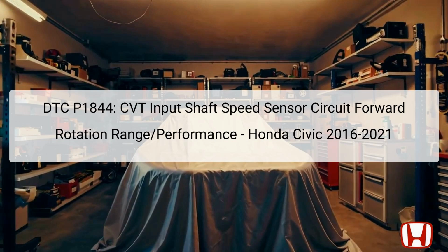The CVT drive pulley speed sensor, which is responsible for this monitoring, is located externally on the end cover of the transmission. It employs a semiconductor that detects the position of the drive pulley and generates pulsing signals that communicate with the TCM. When the rotation of the drive pulley changes, the associated magnetic flux also varies, which gets converted into electrical signals. Inconsistencies between the driving conditions and the detected voltage levels of these signals lead the TCM to recognize a fault and store this code.